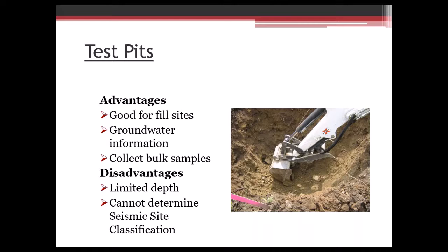Generally, we don't dig test pits much more than 10 to 15 feet. And if we need to get into the excavation for any reason, for any of the sampling or testing, we're really limited to about 4 feet because of the OSHA regulations, unless we start getting into trench boxes and such, which gets a lot more expensive. The other thing is we don't determine any of those soil parameters to get the seismic site classification unless we encounter bedrock at a shallow depth. That's another disadvantage.